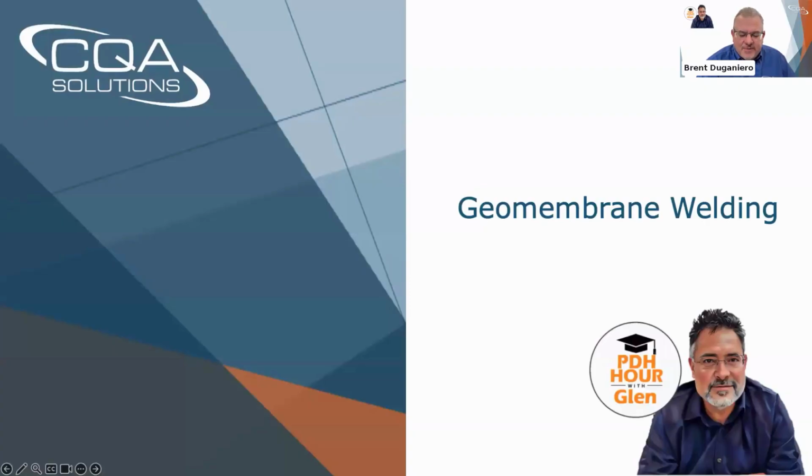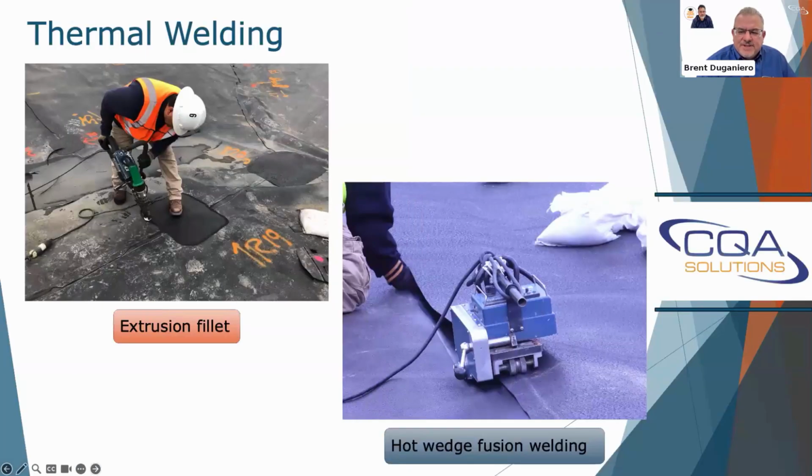All right, so now finally we're starting to weld our geomembrane panels together on our project. Most often you're going to see thermal welding. It can be broken down into 2 different types. One would be the extrusion fillet welds or the hot wedge fusion welding.